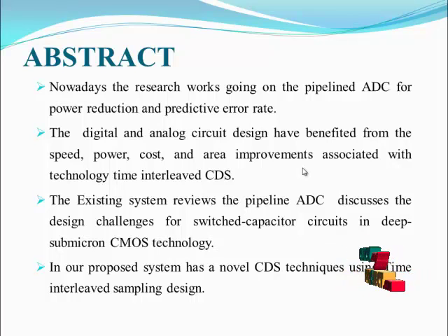However, as the scale of CMOS process continues to shrink, it has become difficult to improve or even maintain the accuracy of the pipelined ADC because it relies on a high gain operational amplifier, that is op-amp, and well-matched components. An immediate problem is that the combination of deep submicron process and low power voltage makes it difficult to realize an op-amp with a high open loop gain without sacrificing bandwidth.